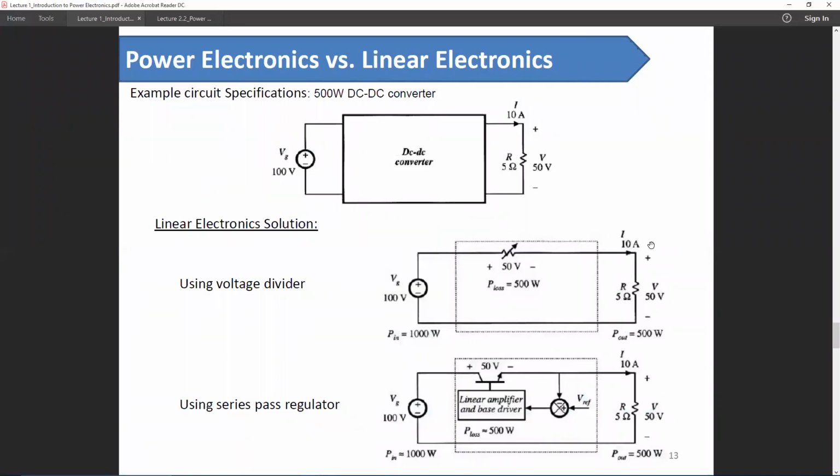So this is a typical example of a voltage divider. It's a resistive voltage divider. If we need 50 volts out of 100 volts, we can easily get it using a voltage divider network. But we have to keep in mind that this resistance is not part of the load. So any power loss associated with this resistance, we have to consider as a loss. In the case of this diagram, you can easily see the loss is 50%. So that brings the overall efficiency of the system below 50%. So this type of approach is not very economical in terms of energy efficiency.